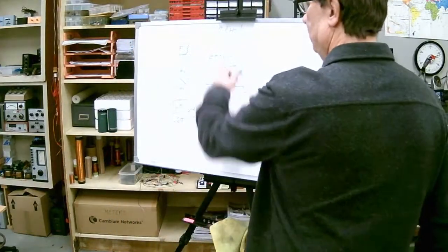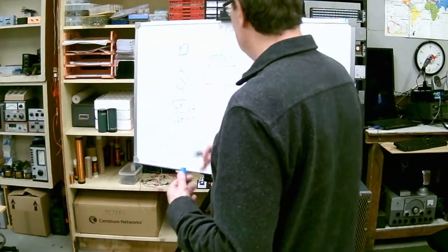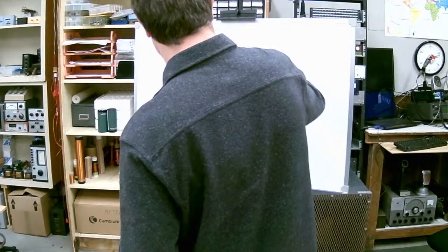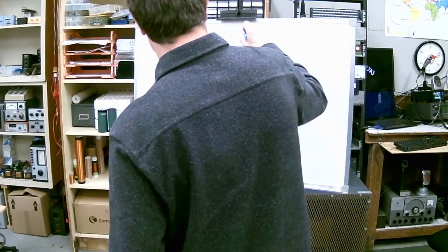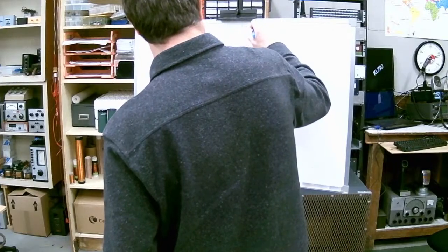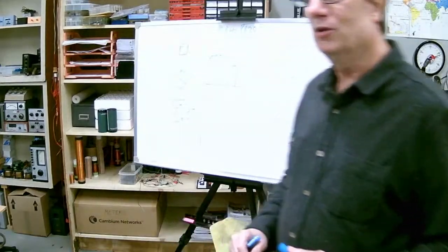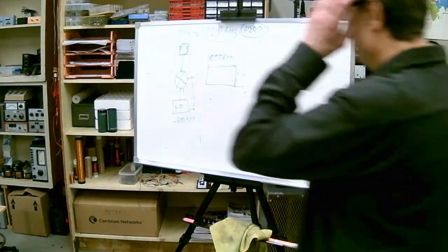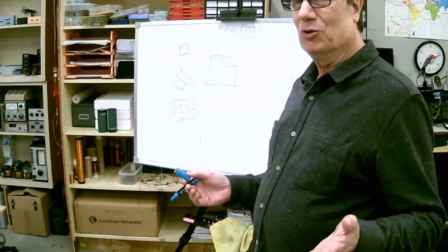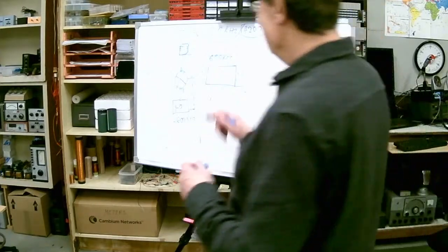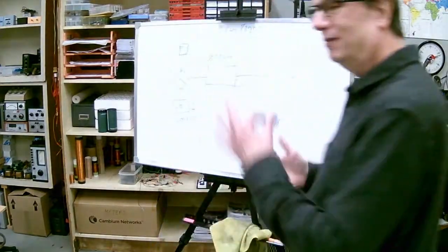And those two, we get the differences out, and we get a high enough frequency that the image frequency would be twice that above that. So the image frequency is 42 kilohertz? Yeah. So there's no problem separating 4200 hertz from here. Sure. But now we have a broad selectivity, like a barn door. So we can't separate closely spaced stations. We got rid of the image, but we can't separate the station.